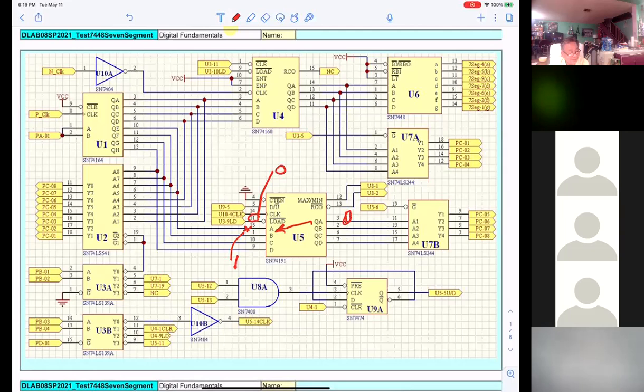Perfect. First thing we want to isolate the wire. Okay? That means you just lift it up. And now you measure at pin 3. If you get a logic 1, that will be telling you the wiring from pin 3 goes to the wrong place.